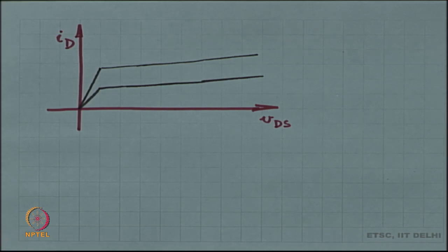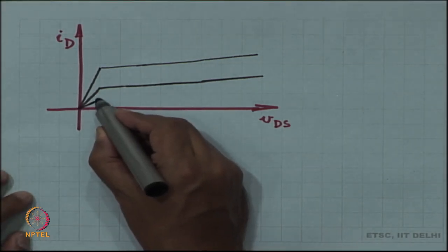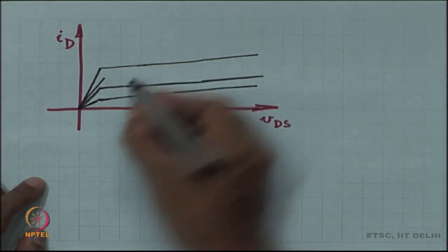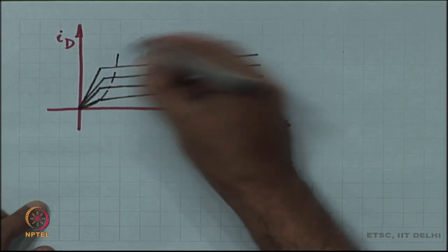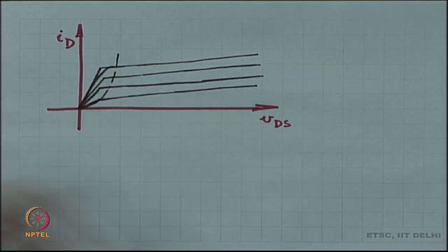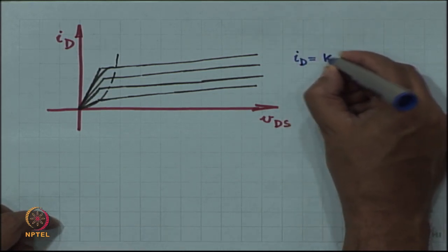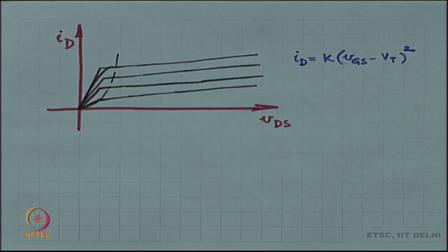All right, so this is what we have. This is the MOS characteristics that I have redrawn. Now, ordinarily in the flat region of the MOSFET, you would say that ID is some constant k times VGS minus VT the whole square. Okay, this is what you would say ordinarily. However, that is not really the case, there is some slope to it.